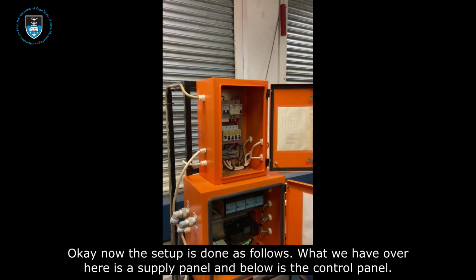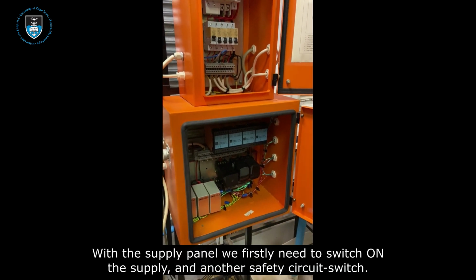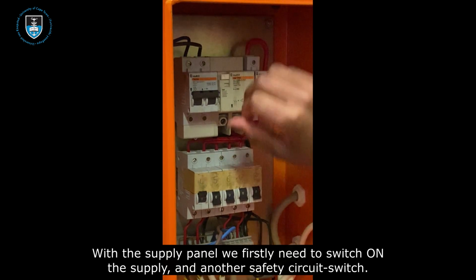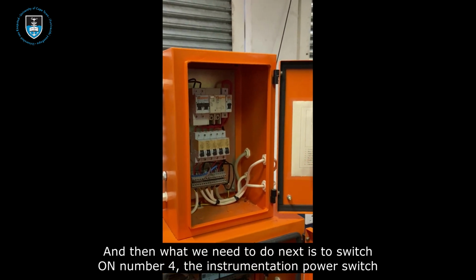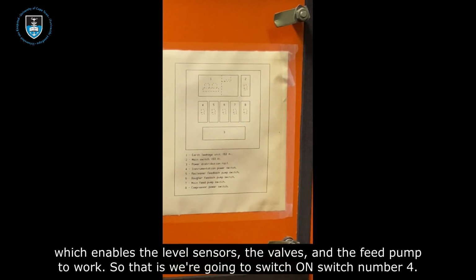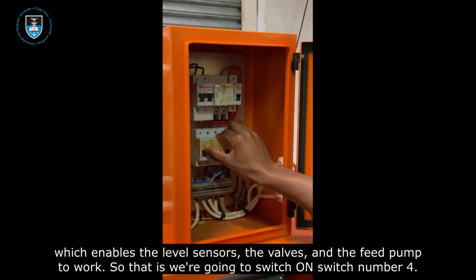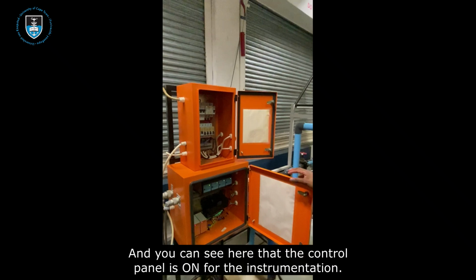Now the setup is done as follows. What we have over here is the supply panel, and below is the control panel. With the supply panel, we firstly need to switch on the supply and another safety circuit. Then we need to switch on number 4, the instrumentation power switch, which enables the level sensors, the valve, and the feed pump to work. So we're going to switch on switch number 4, and you can see here that the control panel is on for the instrumentation.